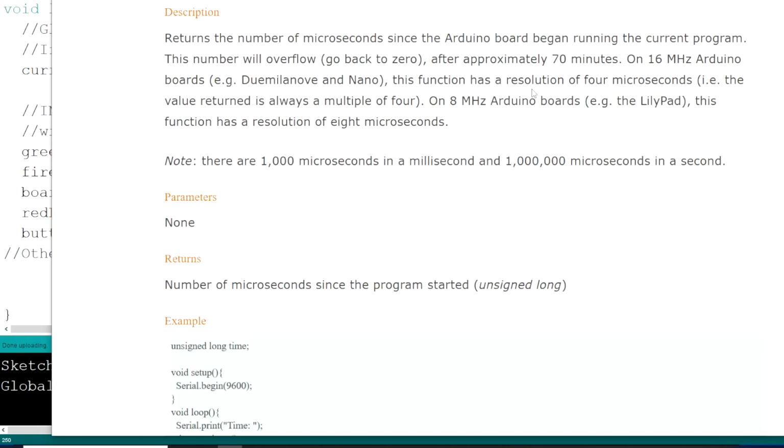Even when it's timing to 1/1,000,000th of a second, the Arduino still has 16 other clock cycles per change in state. So you might think that timer is going up very quickly, once every 1/1,000,000th of a second, but for the other 15 clock cycles your Arduino is sat there bored, twiddling its thumbs. That's how quick these boards can actually be.